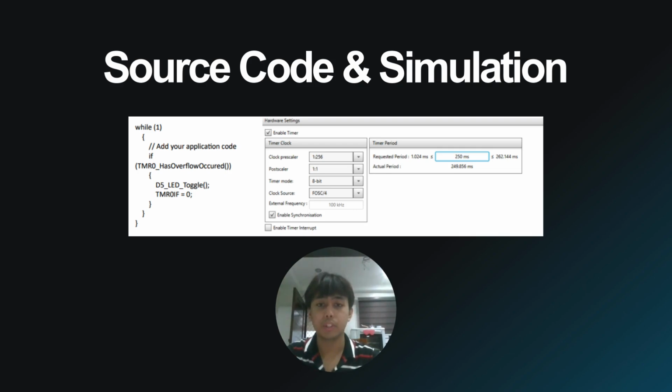The first code used in the main.c file utilizes delay polling. It was observed that the LED switches between on and off at a time interval of 250 milliseconds. This is due to the timer 0 peripheral, where the clock prescaler states the maximum time of the switching. The if TMR0IF statement checks whether an overflow occurred in timer 0.